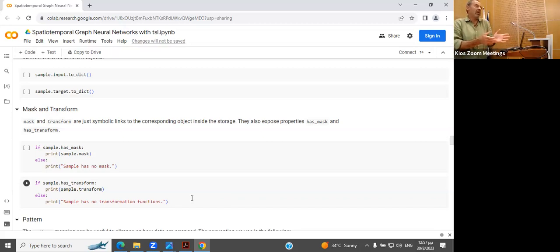Then we tend to compensate because we don't want those effects. We don't like that. If I have a strain gauge and I measure what is happening between here and here, you change the temperature by 1 centigrade, and you will see that value, which is fixed, maybe going up and down. It will change, of course, because you are changing temperature, but it will change because the physical transducer is affected by the temperature. You don't need to compensate that. That is the real value. So you need to change the classes when you look at the physical reality.